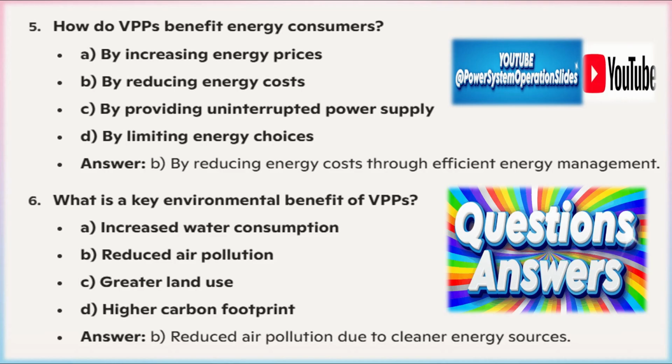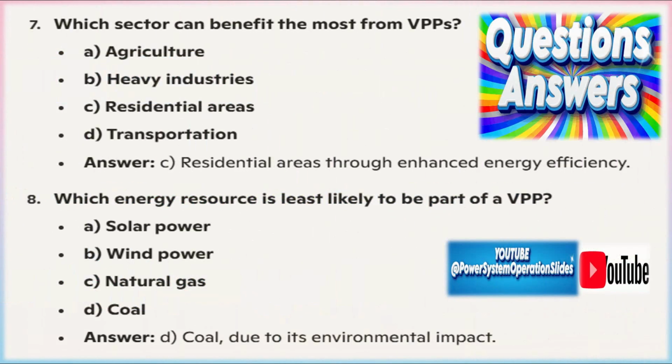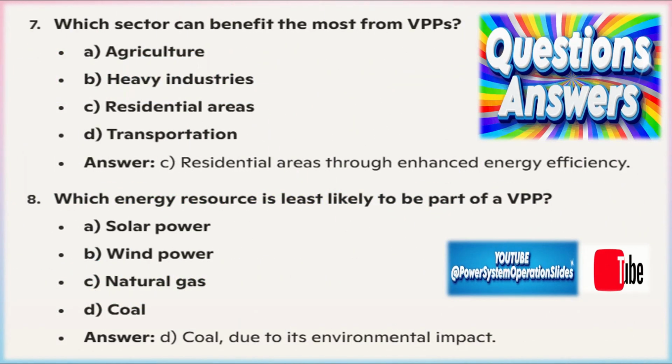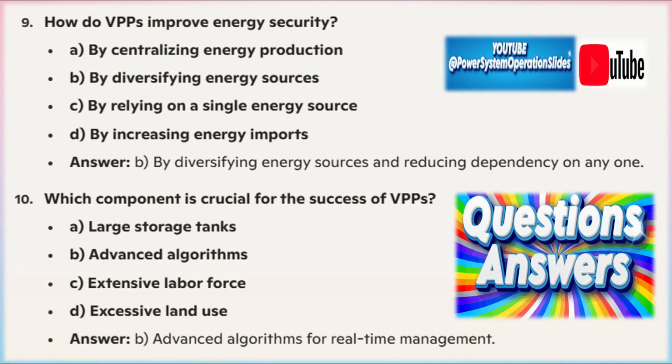Addressing flexibility challenges. Congestion management. VPPs assist grid operators, TSOs and DSOs, in alleviating network congestion by intelligently managing distributed assets. Frequency stabilization. Through frequency regulation services like FCR or aFRR, VPPs maintain grid stability, which is crucial for preventing blackouts. Forecast error mitigation. VPPs minimize the impact of forecast errors by rapidly dispatching aggregated energy or flexibility to cover shortfalls or absorb excess generation.